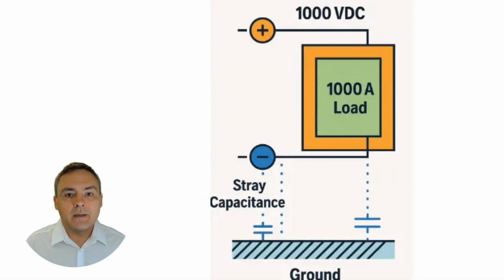There is no such thing as a perfectly equipotentially bonded and grounded system, so I introduced some stray capacitance to introduce some common mode noise. The stray capacitance I introduced wasn't that much, but enough to create some common mode noise between my DC and true ground. I also didn't use shielded cable between my PWM source and the load, at least not yet. This is a very realistic circuit you can encounter if you're trying to do it cheaply.